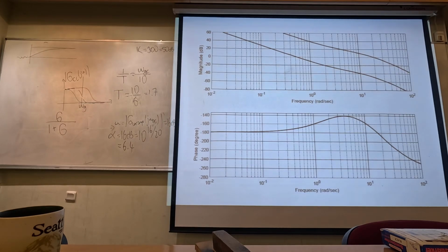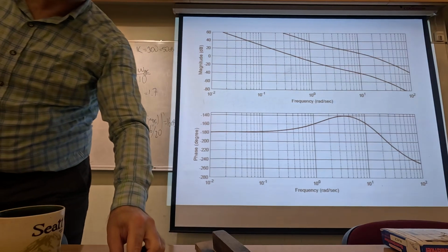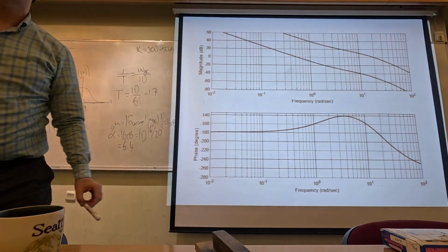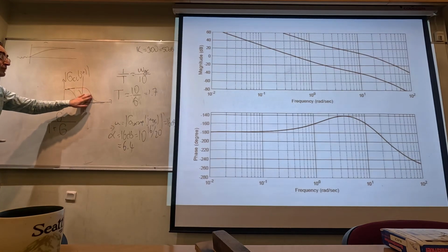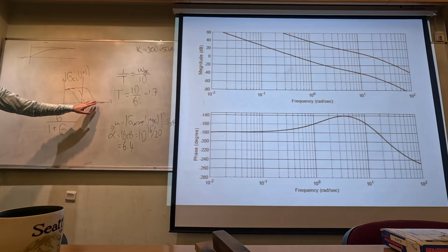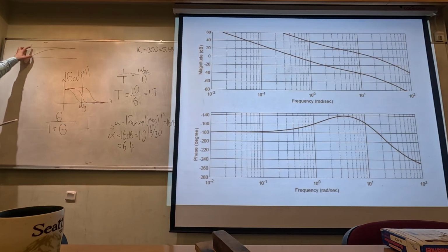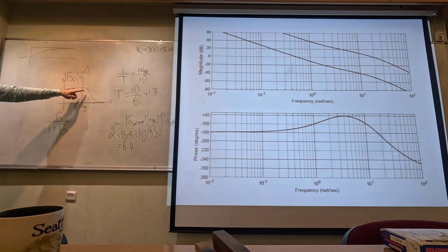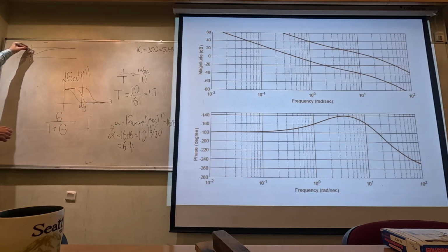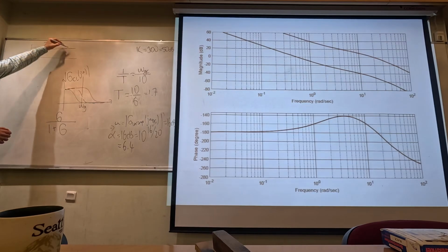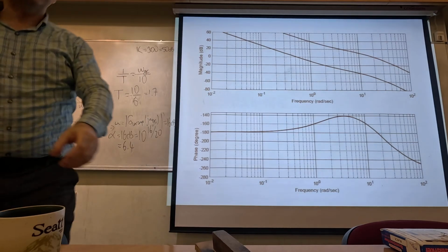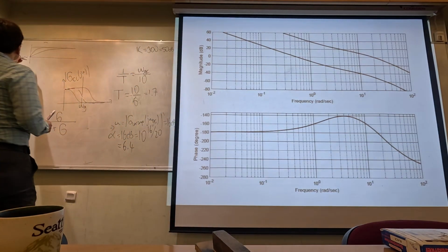Okay? For the low pass filter with the red frequency response, the response is going to be faster. It is going to pass more high frequencies. Okay? This sharp change is going to be less smoothed in the red low pass filter. So the red response would be looking like this. And if you look at the green response, it's going to be even slower.